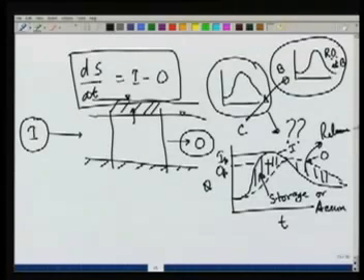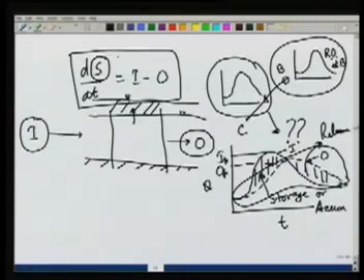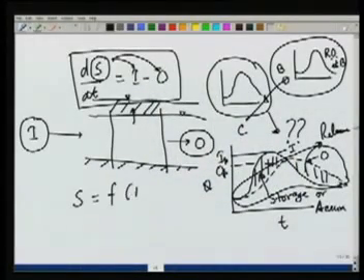And the aim of all these routing, flood routing or storage routing, is to obtain this curve for O, given the curve for I, and for that we need some kind of relation between S and I and O. For example, in the Nash model we have assumed a linear relationship between S and O, but in most cases S will depend on both I and O, and therefore typically we write S as a function of both I and O. And there are different methods which we will discuss later on for routing a flood through a reservoir or a channel. Right now we will not go further into this discussion, but this S has to be described as a function of I and O.